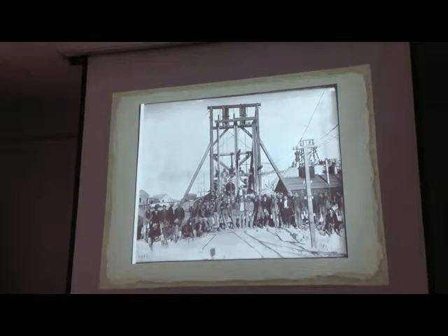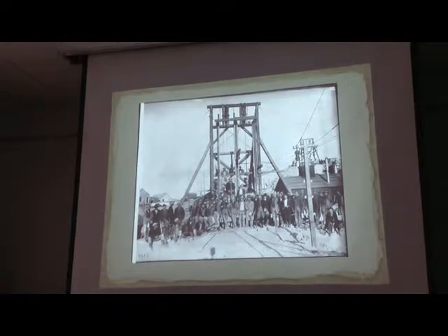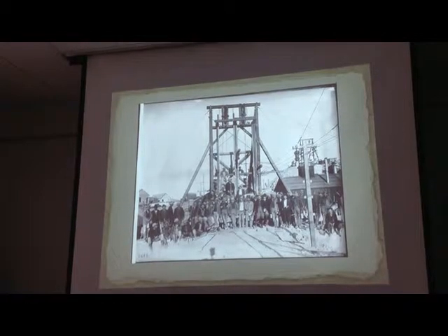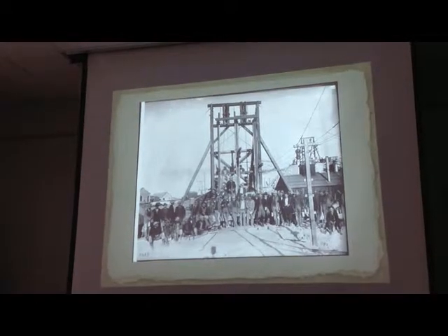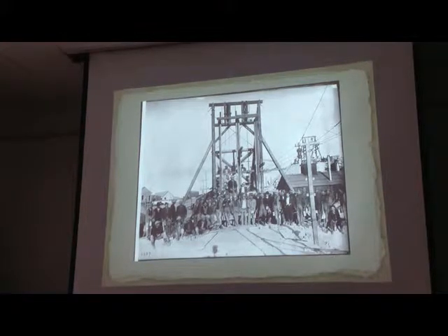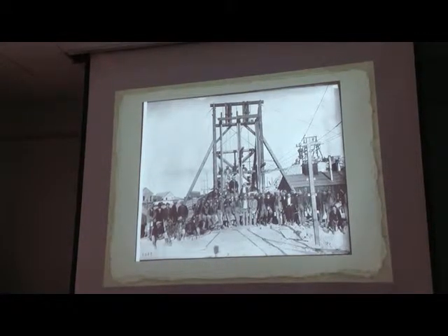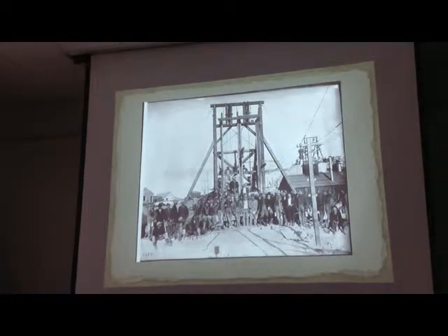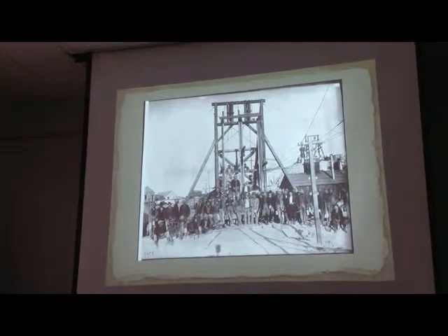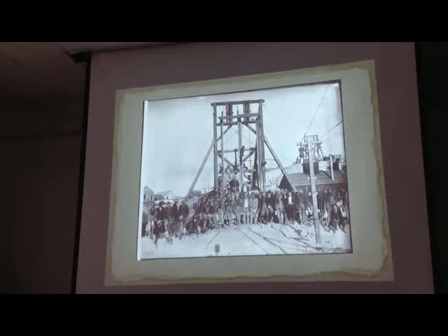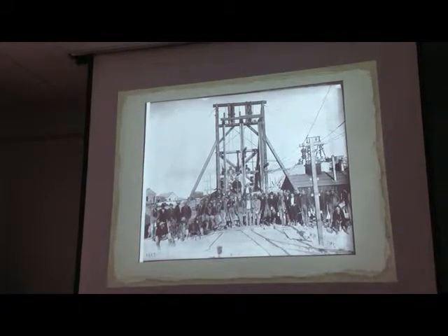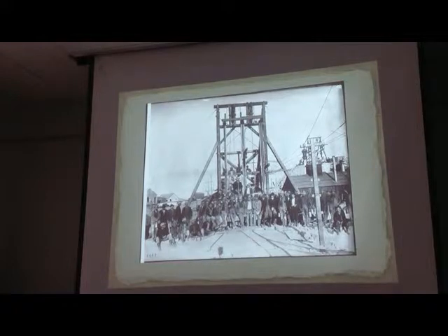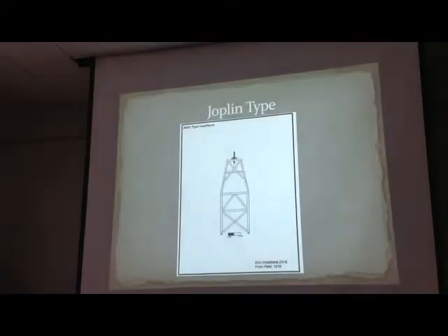Now you can see what the problem is here. You've got your basic two-post head frame design, but they're hoisting so much that it's having stability problems. They've got braces on the sides. They've got guy wires. This one has tie rods in it, so this would have been early 20th century. And that's one of the problems with the two-post. It's not a very stable design. You can get to rocking, the more vibration you get, you can actually just shake it apart, which is why they went out of fashion.